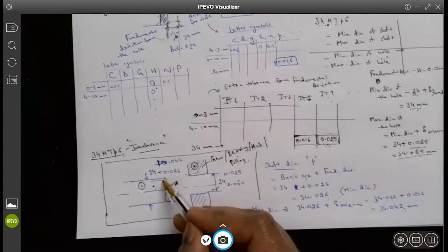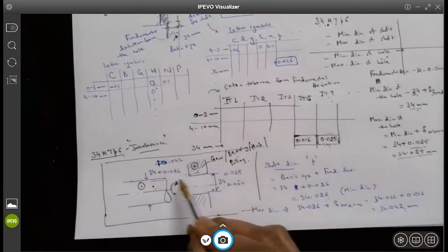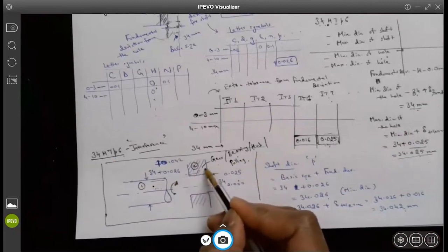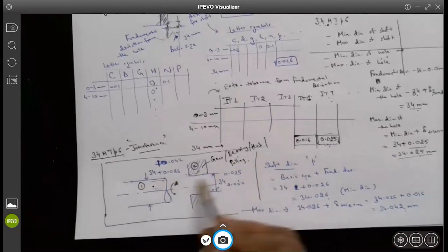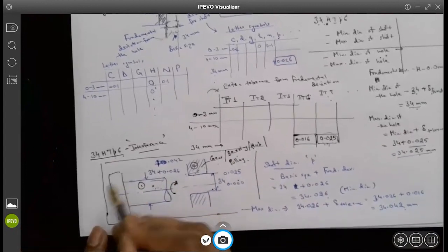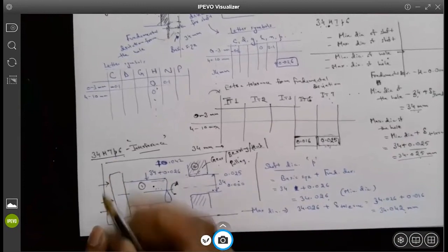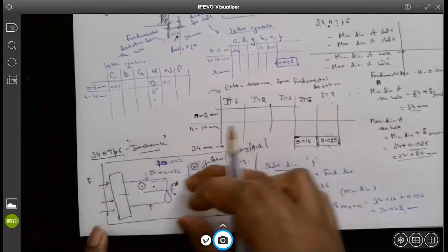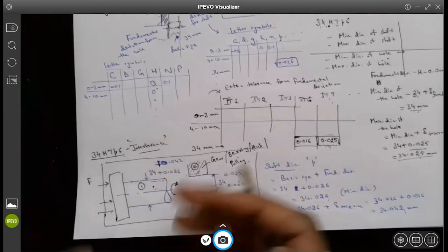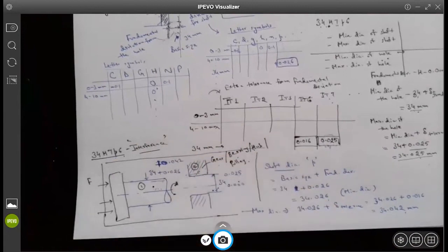When you press this part against this part, there will be slight deformation on the hole, and slight deformation on the shaft. Once you apply a pushing force from a press, this part will get assembled or stick inside this hole, based on the type of interference you're going to get. Make sense?